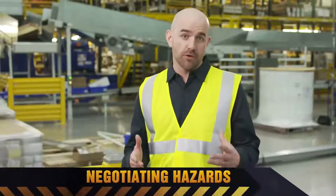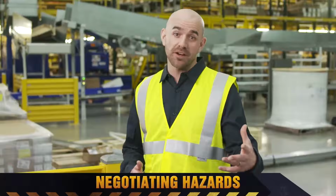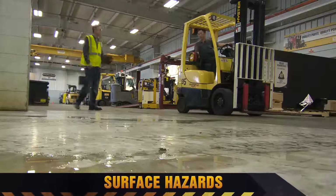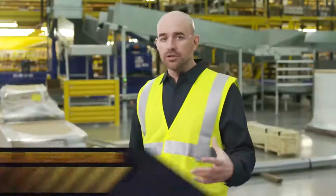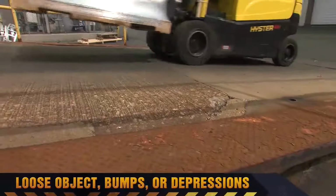Every time you operate a forklift, you'll need to be on the lookout for potential hazards. It'll be up to you to find a way to negotiate these hazards safely. Let's take a look at some pretty common examples. You'll probably encounter wet, oily, or icy surfaces along your route. Avoid them when you can and get someone to clean them up as soon as possible. Any loose objects, bumps, or depressions in the floor can cause you to lose control of the steering, bring the forklift to a sudden stop, or tip the forklift.